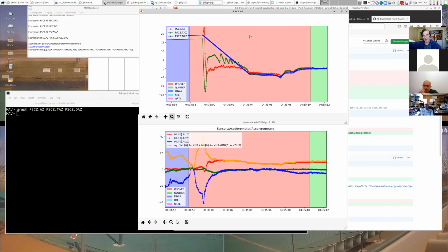Which means on the final approach for landing, it does drop the motors way down. We don't drop them to 0. We have a throttle minimum, I think, of 15%. So you keep some attitude control, right? Because otherwise it's not quite balanced perfectly, and it does tend to nose into the ground. So you need a little bit of throttle there to allow it to have attitude control. But that means you can slow down a lot on the approach, and for those auto missions, it actually only gains about 3 meters on the back transition. But in this case, the pilot was flying it along at 20 meters a second, which means you don't get that opportunity.